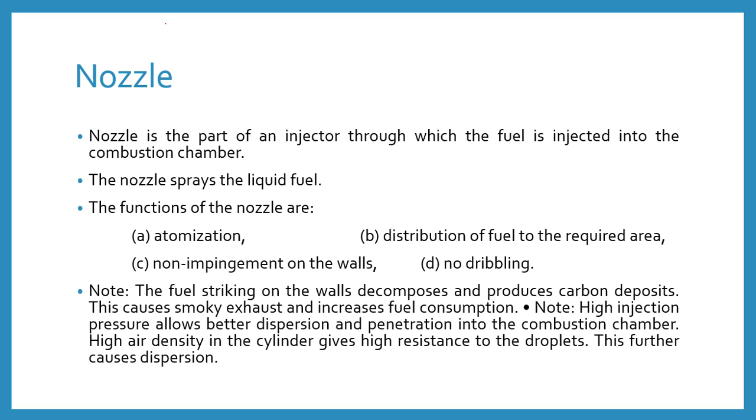Second, the high injection pressure allows better dispersion and penetration into the combustion chamber. High air density in the cylinder gives high resistance to the travelling fuel, which further causes dispersion. These are the basic notes on the fuel when it is thrown from the nozzle.